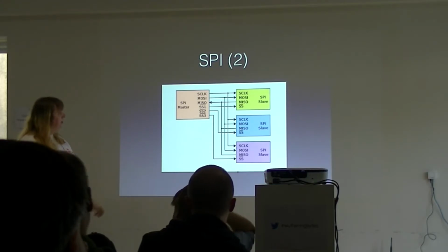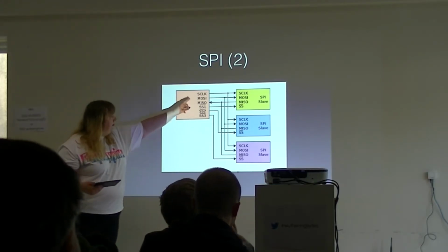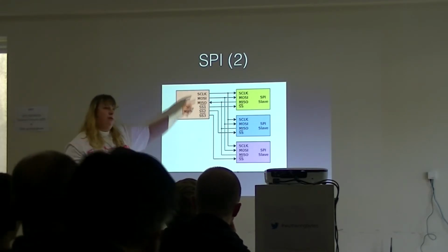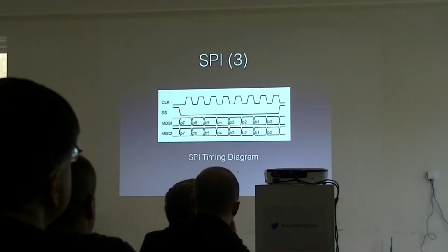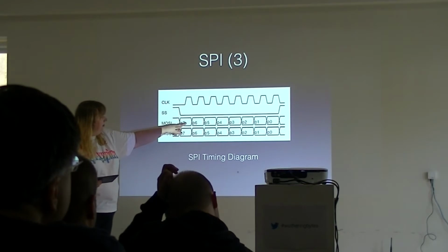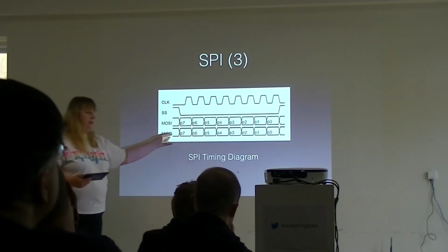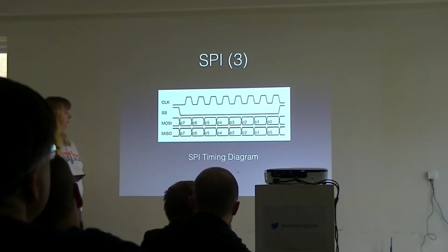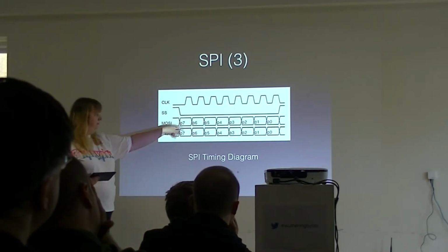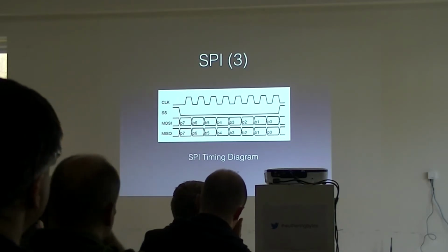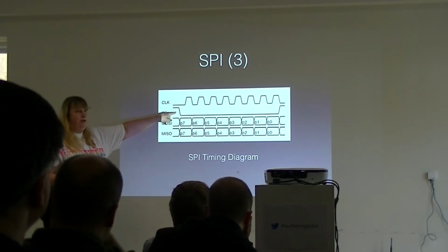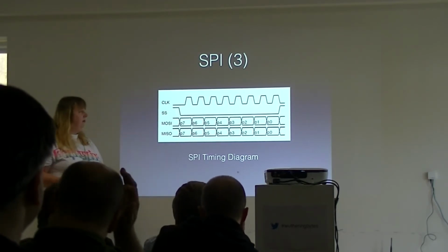But again, it is just putting data on the output pin and pulsing the clock. In fact, there's a picture. So, pulse the clock, and the data goes out, and the read data comes in. For whatever reason, it's always the high bit first. And that's our select line, the one that shows which device we were writing to.